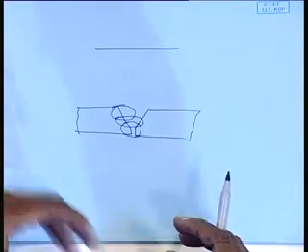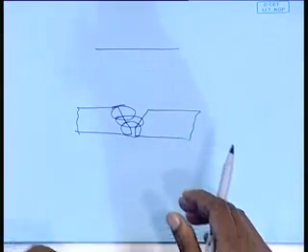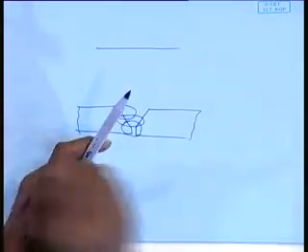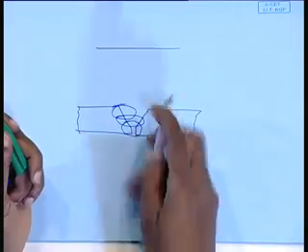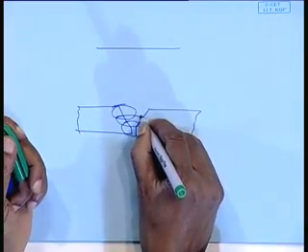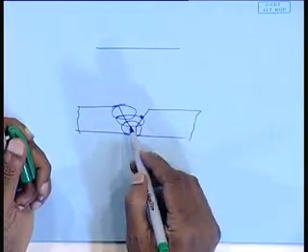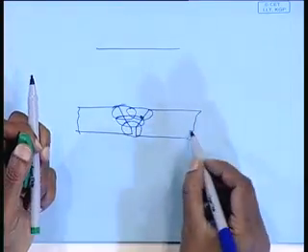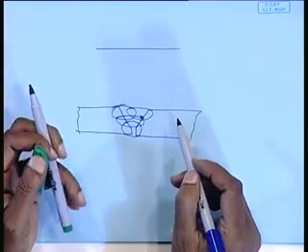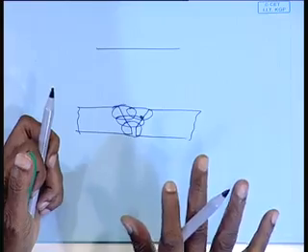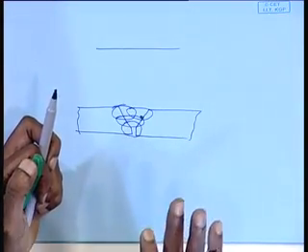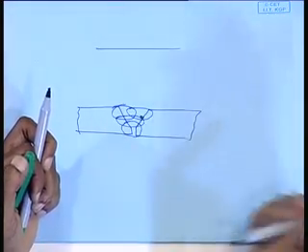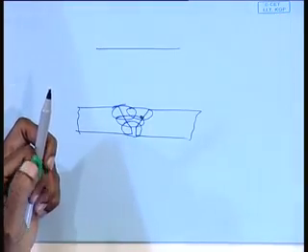Every run you are giving, you are removing the slag. If you do not remove it meticulously, a small speck of slag may remain inside. Suppose a slag has remained here and you have done welding on top of it. What will happen? The slag does not get remelted, neither does it float up, it remains. So that is a slag inclusion, the slag has got included.